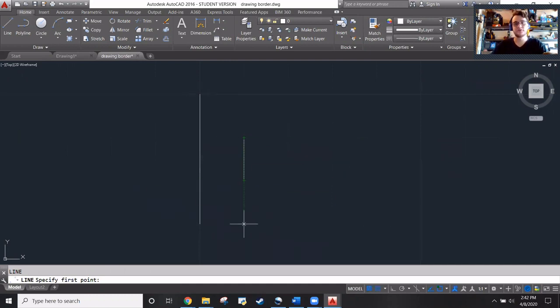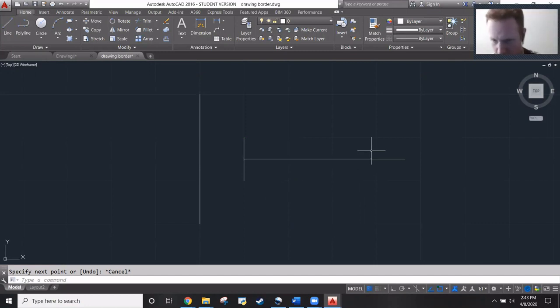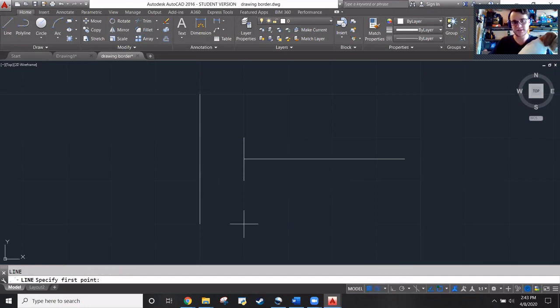Now I've got a problem because I have grid snap on, but I want to actually draw my line to the middle of this existing line. So I guess let's turn grid snap off, because that will allow me to go in and snap to the middle of that line. Did everybody see what I did? Does snap midpoint not work? Okay, so that's the thing. Sometimes you'll get settings that are basically fighting each other. If I leave grid snap on and I try to use, oh wait, that did work actually. That's super weird. It wasn't showing up on the other one. Let me try that again.